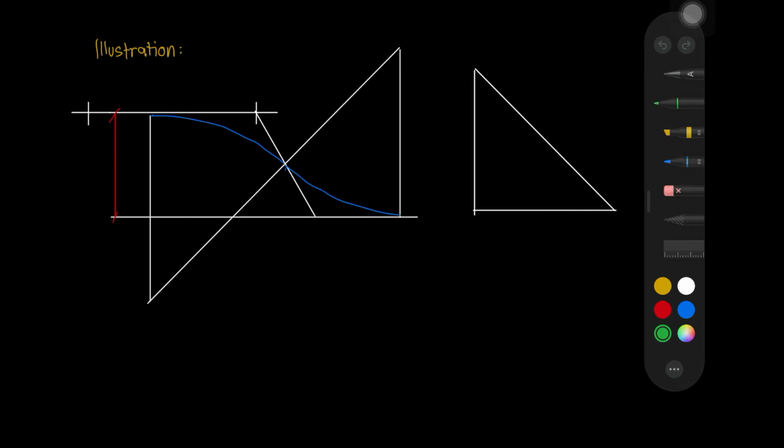I already have a pre-illustration right here. The azimuth of the back tangent is 270 degrees, so that means this is our T1. And the azimuth of our common tangent T1 plus T2 is 300 degrees, which means this is also our T1 and this is our T2, which makes this line our T2 also. From the problem, our offset or the perpendicular distance is 30 meters.